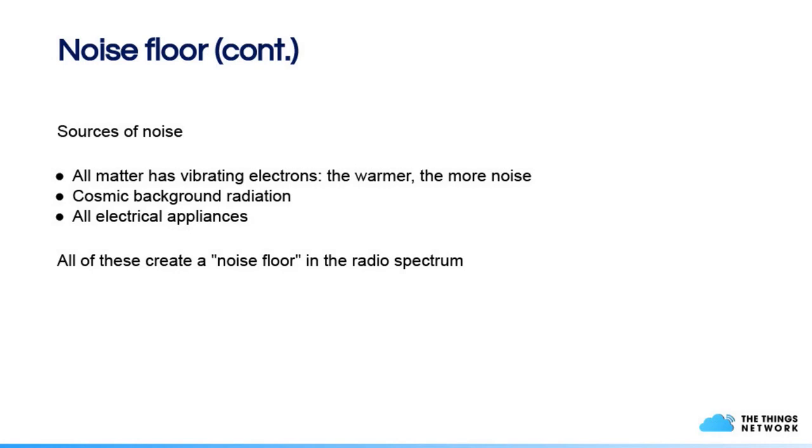What did we hear? Noise? Yes, this is the noise floor. But where does this noise come from? All matter is built up of atoms, and these atoms have vibrating electrons around them. Moving electrons cause an electric and magnetic field. The warmer the matter, the faster these electrons vibrate, and the stronger these fields will be.